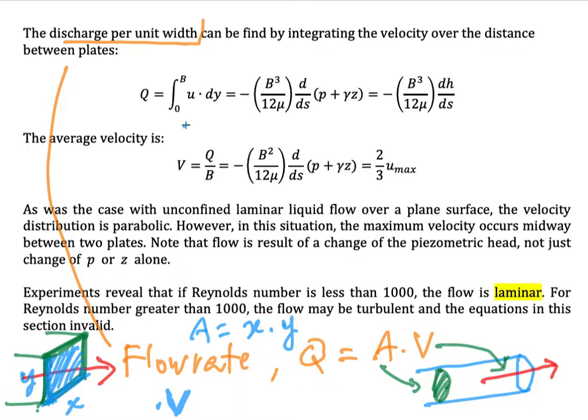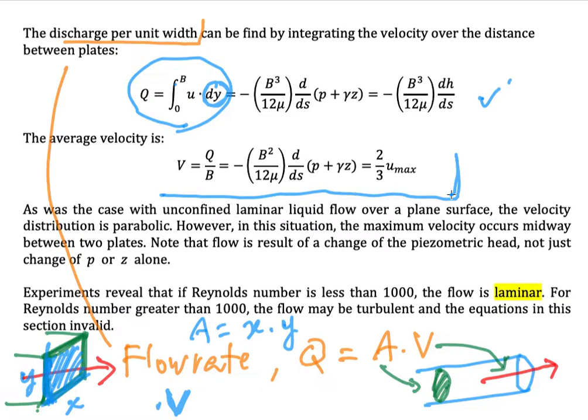So in this calculation, we could calculate q as the integral of u times u dy. The dy here only shows the height of this one. Then we could get the value of this one. If we compare with the experimental work, we could say that the average velocity is actually 2/3 u max. This is actually the result from the observation.